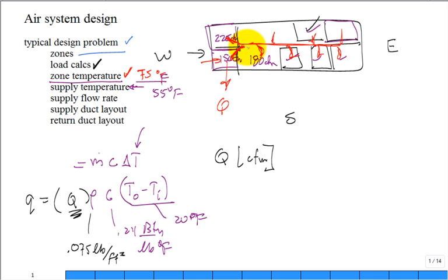Anyway, we're going to get the flow rates to each place, and we have a general layout, and now you can just do the math. It's pretty simple. If I need 225 CFM in that run right there, 225. And if I need 150, I need 150 there. But if I add them together, I'm just working backwards. I need 225 plus 150.